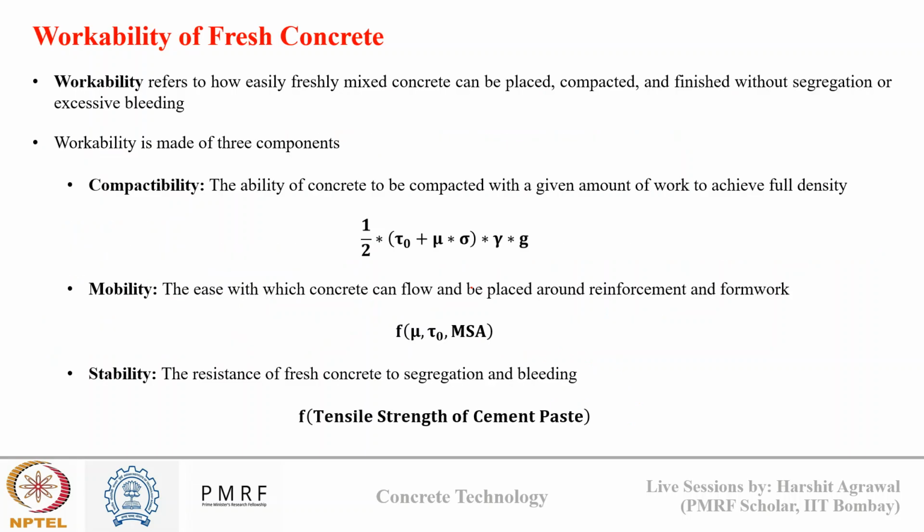Now, one part in transportation that we need to discuss is pumping. Okay, but before moving into pumping of concrete, let's discuss one important property of concrete which affects the transportation, which is workability of concrete. So, workability refers to how easily my freshly mixed concrete can be placed, compacted, and finished without any segregation or excessive bleeding.